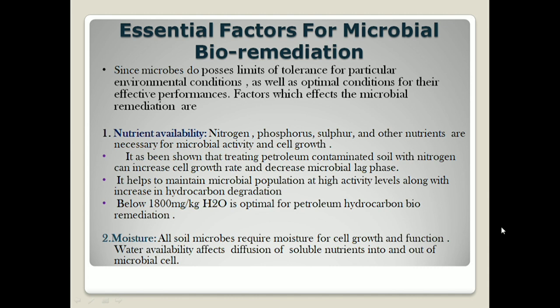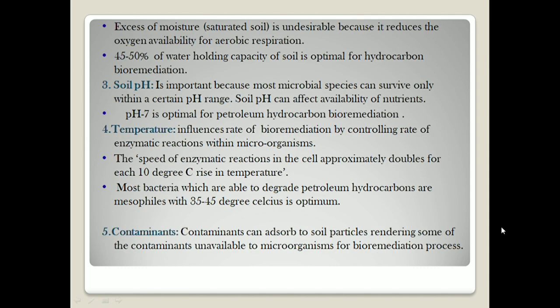Next, moisture. All soil microbes require moisture for their growth and function. Availability of water affects diffusion of water and soluble nutrients in and out of the microbial cell. Excess moisture is undesirable because it reduces the oxygen availability for aerobic respiration. 45 to 50% of water holding capacity is optimal for petroleum hydrocarbon degradation.